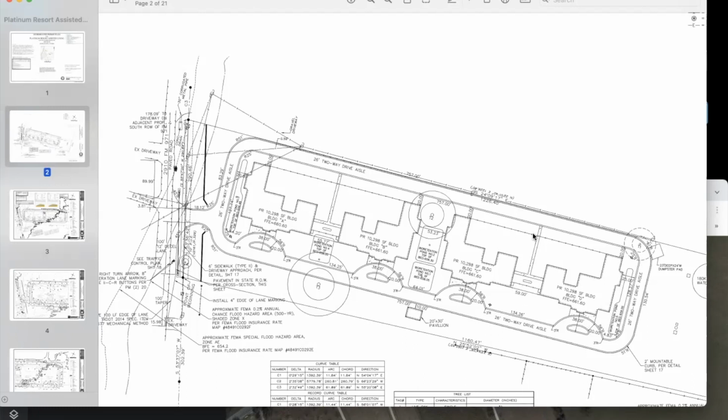This little dotted line here, this is a backyard fence there and there. That way when you're in the back, the residents can't leave and it feels more like a home. There's a front yard fence or like a side yard fence between the 2 buildings, but ultimately they're sharing just one big backyard. This is sidewalk here because staff parking is parallel parking here, or they may be able to just pull in right here because this is actually 20 feet of a setback where they can potentially pull in or parallel park here. But the road specifically is 26 feet wide.